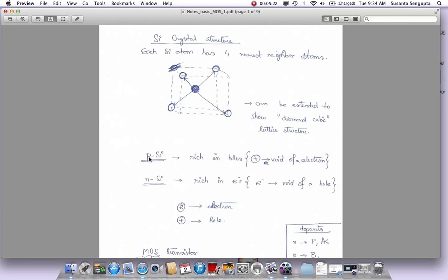So this is the silicon structure, but what we normally use is we don't use silicon as such. Silicon is there, like if you take sand, it is nothing but silicon dioxide. That's what pretty much sand is, and from the sand you can extract silicon. You take sand and heat it up to an extremely high temperature, you will break the bonds between silicon and oxygen. Oxygen will go out, and what will be left with you is pure silicon. It will be molten silicon, and then as you cool it very gradually, you don't do it fast, you do very, very slow cooling, then it will come back to a structure like that, and you will get pure silicon as an element.